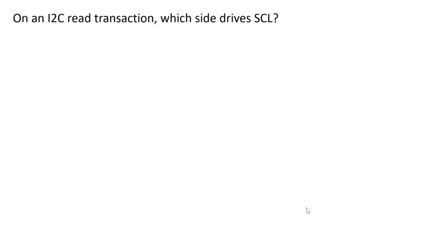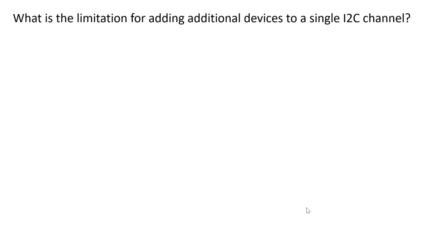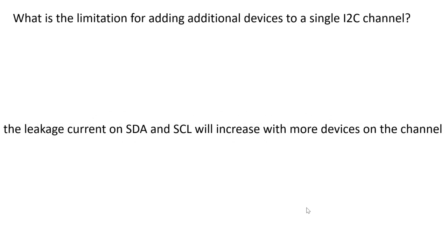Okay, let's see. On an I2C read transaction, which side drives the clock? Always the master. That's easy. What's the limitation for adding additional devices to a single I2C channel? Leakage current, because it's open drain.